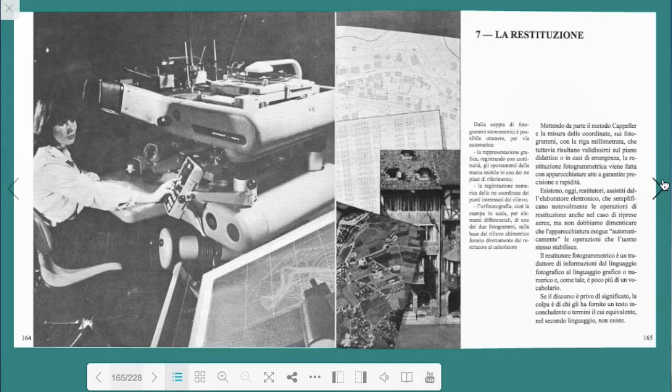Oblique shots should not be neglected, obviously renouncing to obtain scale prints from the same frames, for which the use of long focal lengths with a vertical optical axis becomes indispensable. It is not risky to argue that, even in the case of aerial photogrammetric surveys, the client must collaborate in finalizing the survey, participating in reconnaissance flights. Finally, remember the possibility of requesting color shots, both in normal and infrared emulsion, for particular applications.